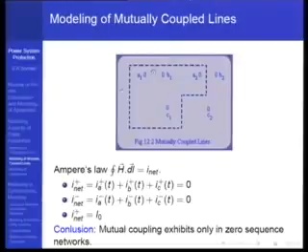Now if your excitation is positive sequence, you know from Ampere's law that the total MMF, the H into L product throughout this circle, is nothing but the net current inside of it, which is IA plus IB plus IC. If a positive sequence current is given to ABC, then the net current is 0. So no net flux links A2, and therefore the mutual coupling between circuit 1 and circuit 2 in positive sequence is 0. The same reasoning applies for the negative sequence also.